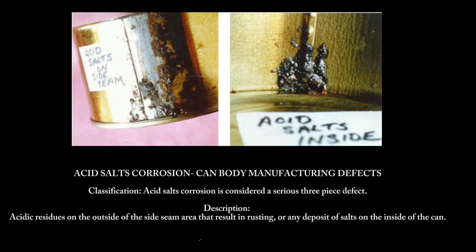If not properly rinsed or neutralized, the acids can trigger corrosion over time, compromising the can's integrity and potentially affecting the product inside. So proper cleaning and maintenance during the soldering process are essential to prevent this defect.